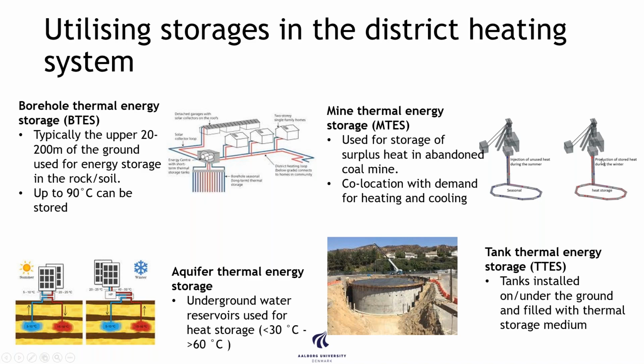We can have a mine where we drill a mine, and we have a heat storage, both seasonal, or we can use underwater water reservoirs for storages, and then we can use a tank thermal storage, either underground or overground. Some of these are more seasonal storages, where you can have long-term seasonal storage, like the borehole thermal storage, or we can have a tank thermal storage, which can be more day-to-day.